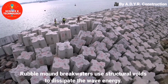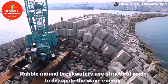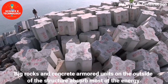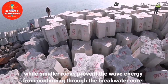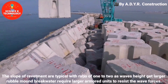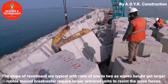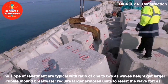Rubble mound breakwaters use structural voids to dissipate the wave energy. Big rocks and concrete armored units on the outside of the structure absorb most of the energy, while smaller rocks prevent the wave energy from continuing through the breakwater core. The slope of the revetment is typically a ratio of 1:2. As wave heights get larger, rubble mound breakwaters require larger armored units to resist the wave forces.